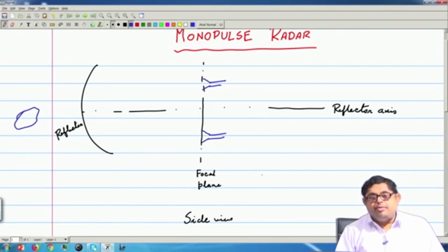So, then people found out from experiments that you can get the exact thing if you do ratioed measurement. We have seen that in the vector network analyzer also, this ratioed measurement, that means if you take the ratio of the received signal with respect to a reference, that is a very good thing.